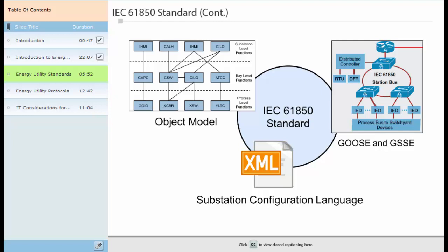A configuration language that exchanges configuration information between the tools used for substation engineering. To address this requirement, the standard specifies the Substation Configuration Language, or SCL, which creates a hierarchy of XML-based files that describe devices and their capabilities.